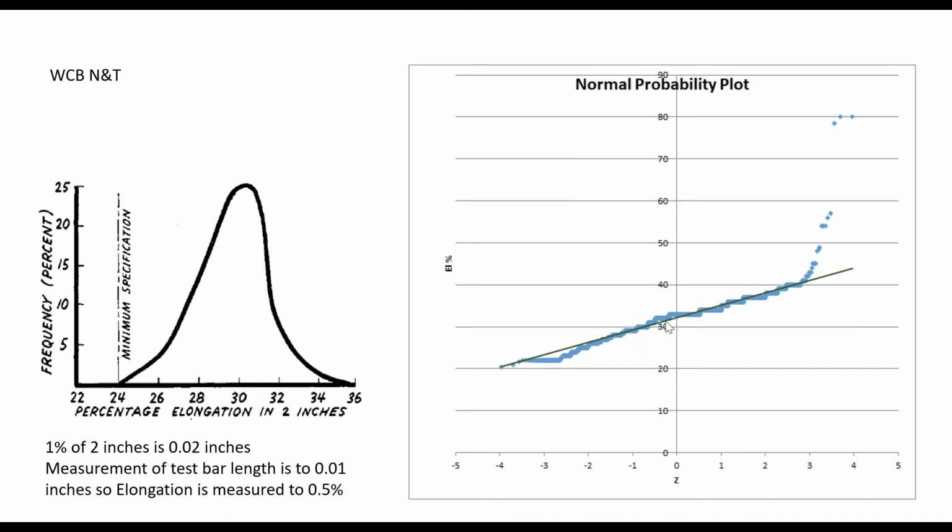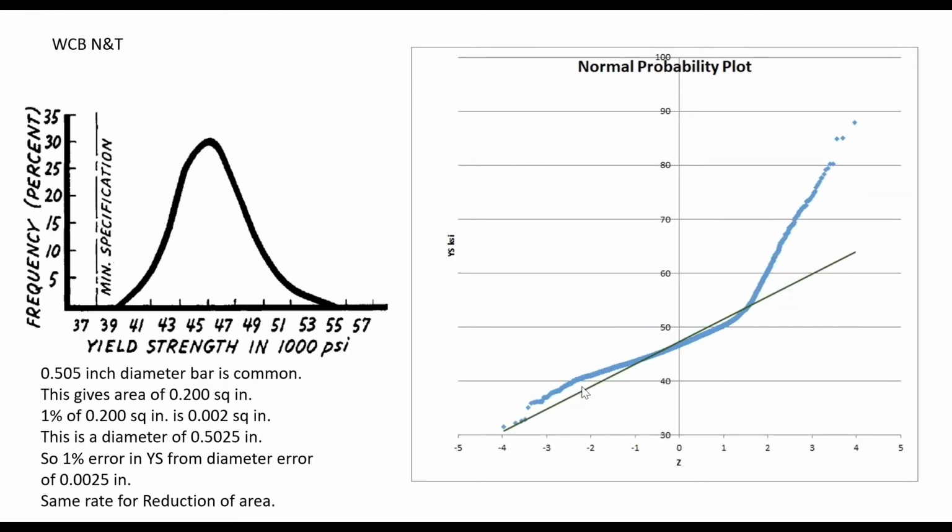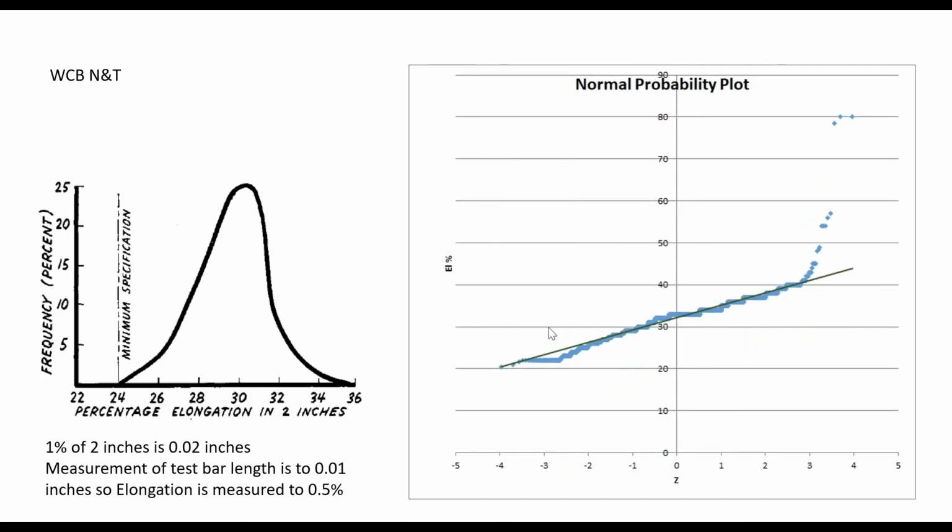And that's why you see this stair-step behavior here that you don't see here, because we get really nice measurements for our loads off of the equipment. But in terms of elongation, at least for steel, we take the instrumentation off so we don't break it when the specimen breaks, and then we put the specimen back together to try and get that measurement.